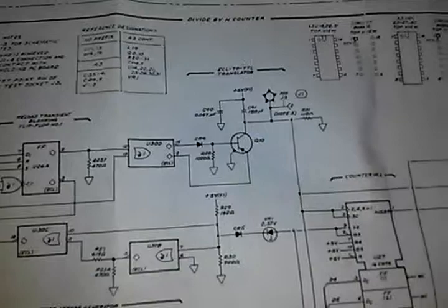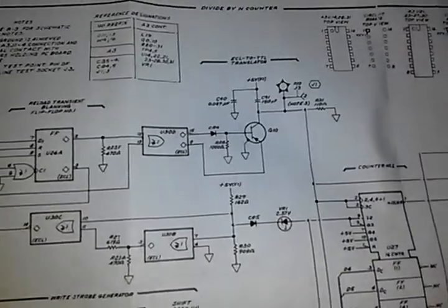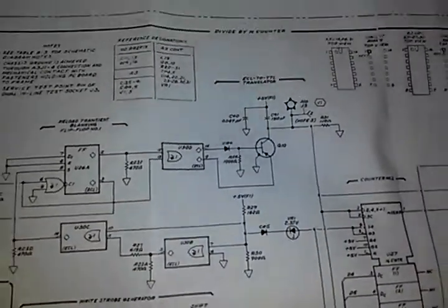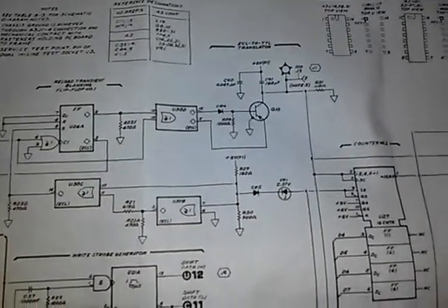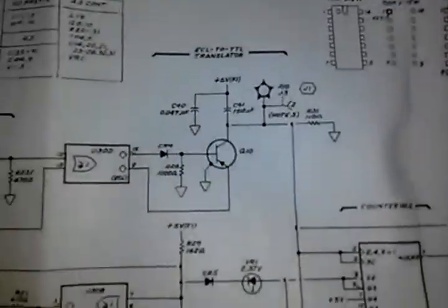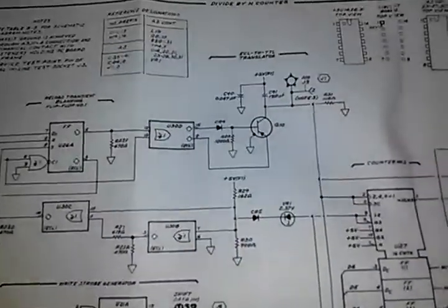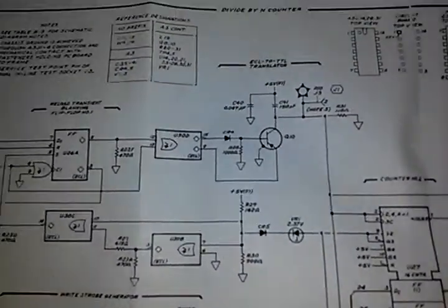Now, I pulled that transistor. I do not have a curve tracer, and I checked it out in the simplistic fashion, just basically doing diode checks, and it was okay. I also checked out the capacitors, and they were okay. I checked out the diode, and it looked okay, which was pretty stupid, but I just figured I'd change it anyway.